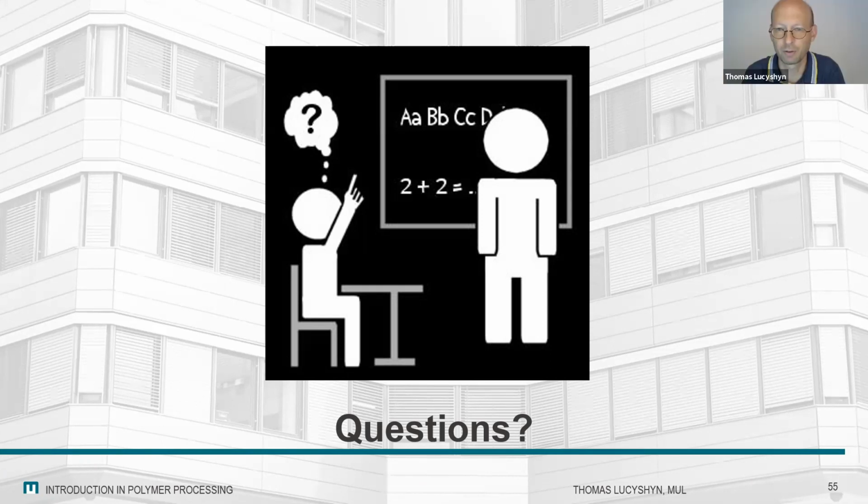I would say if you have a look at the final product, so if you're extruding a film again or a pipe, the problem is that the relation between surface and volume is not the best. So you have a material, a product. With the washing process, you cannot reach into the product itself. So I'm not sure if the effectiveness is so high. If you're applying washing in the pellet state, you have a better ratio of surface to volume, and therefore maybe you can more easily extract some odors or something.